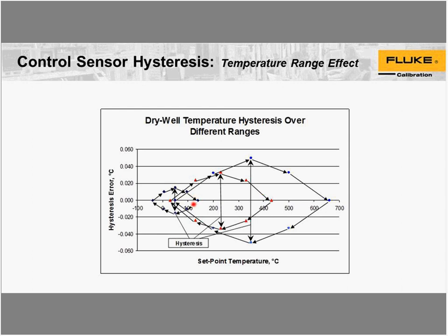So how will you test for this hysteresis? You have to start with a reference thermometer that is of very high quality, that exhibits very little hysteresis. Given that, you'll cycle that dry well calibrator over the temperature range that you intend to use it.